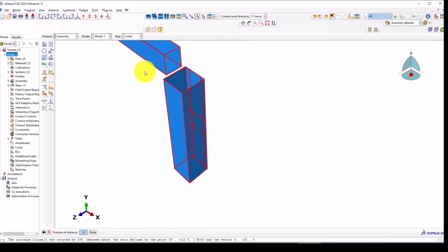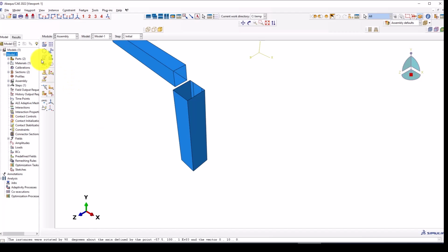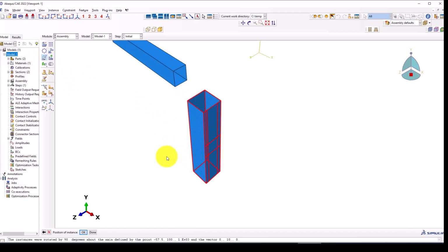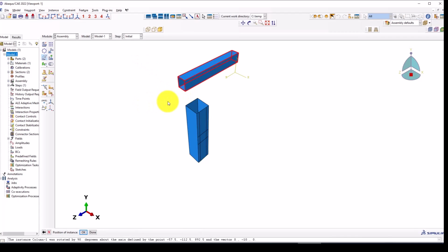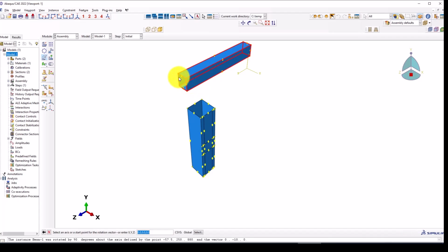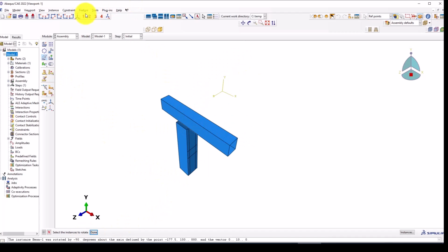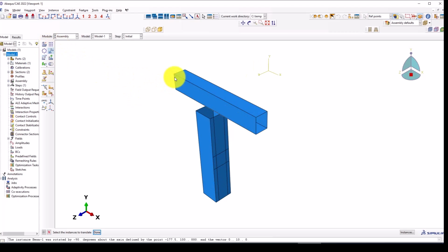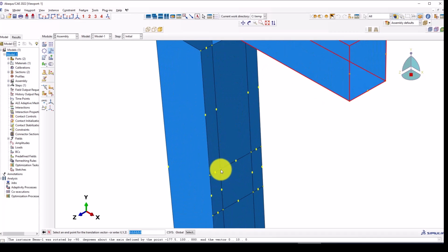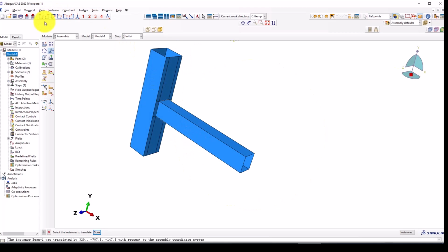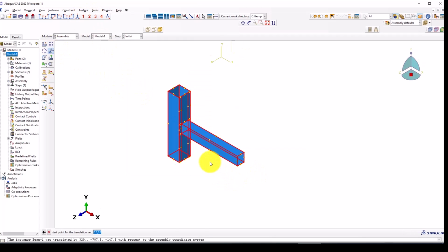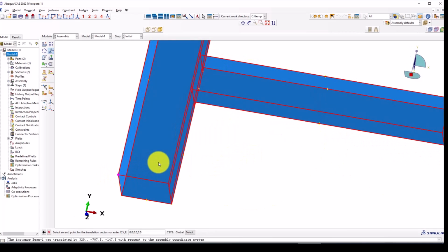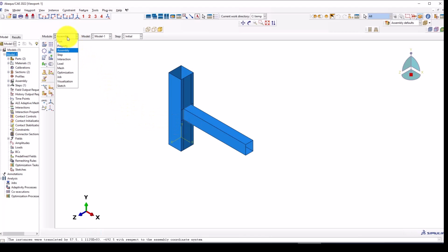So this is the beam. So you should take this one, and again going to be here. Okay, and this time select this one and select this one more, and instead of giving 118, I'm going to go back here and give minus 90. And now I can use the translate option, and I'm putting this point to this point, so exactly in the right location. Now I can go here and see it's correctly adjusted. I'm going to move all, selecting that point to 0 0. Now here we finished the assembly.